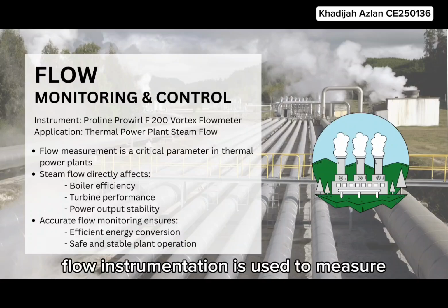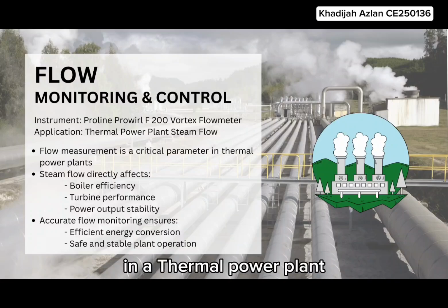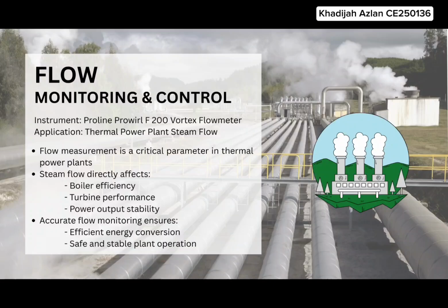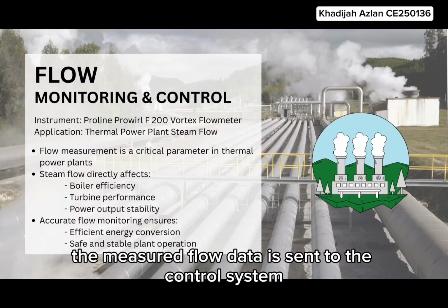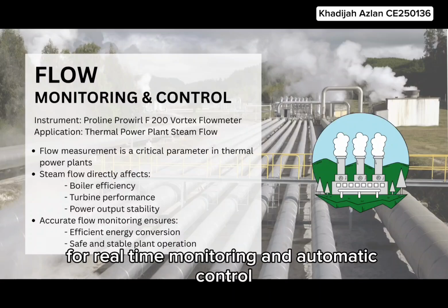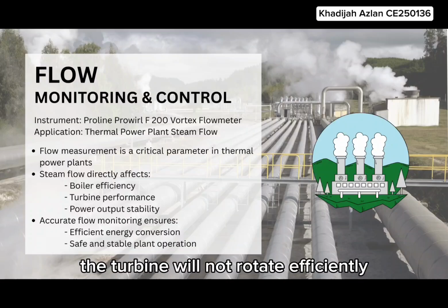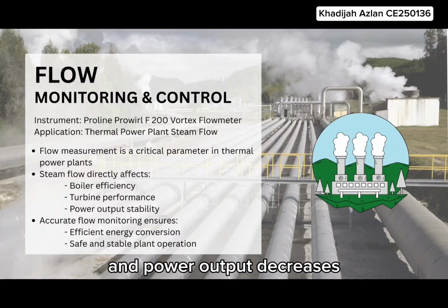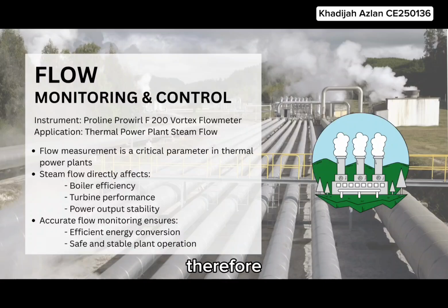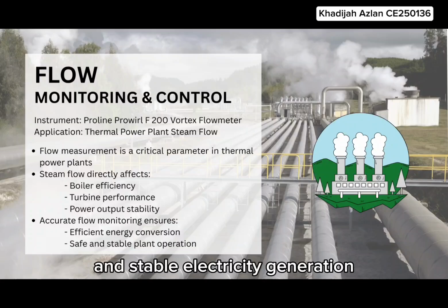Flow instrumentation is used to measure, monitor, and control steam flow inside the plant. In a thermal power plant, flow meters are installed at the boiler outlet or turbine inlet. The measured flow data is sent to the control system such as PLC or DCS for real-time monitoring and automatic control. When steam flow is too low, the turbine will not rotate efficiently and power output decreases. When steam flow is too high, it causes mechanical stress and damage to the turbine. Therefore, controlling steam flow helps maintain safe operation and stable electricity generation.